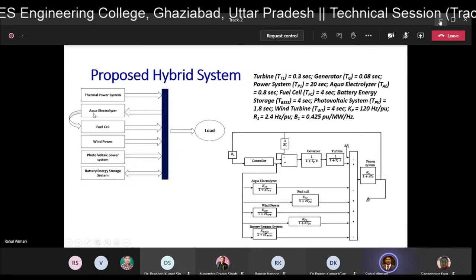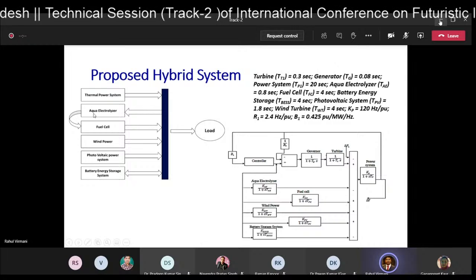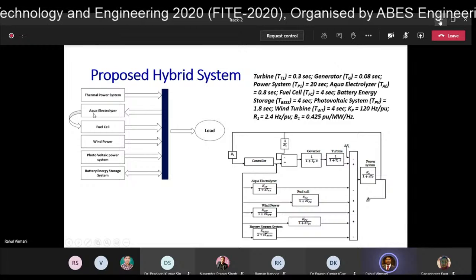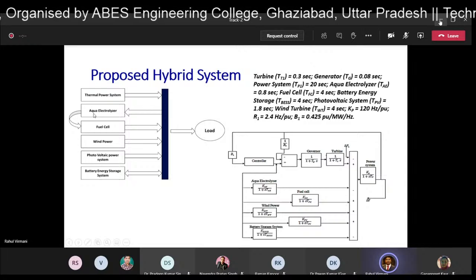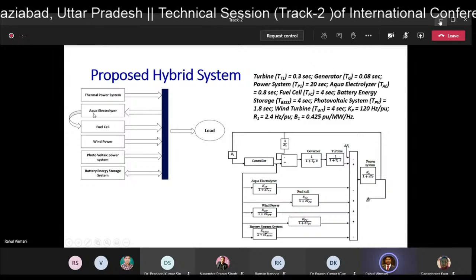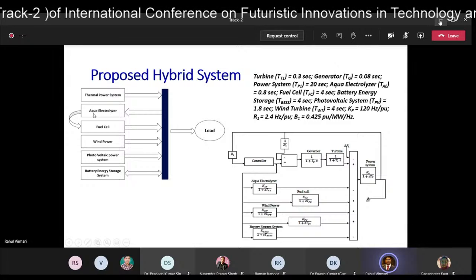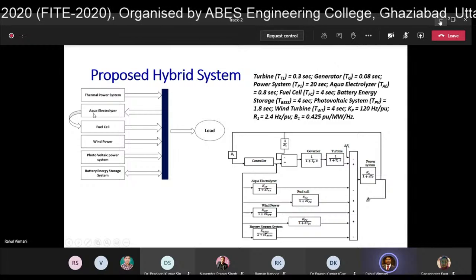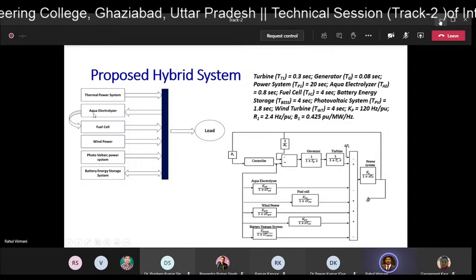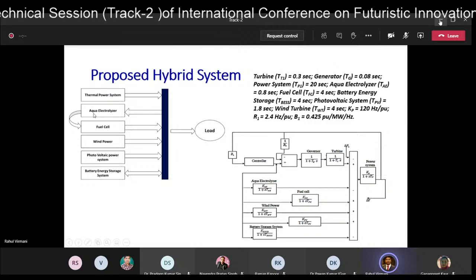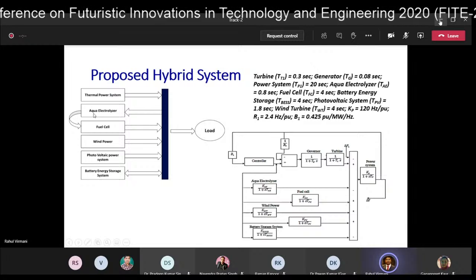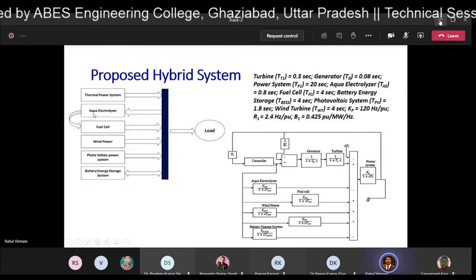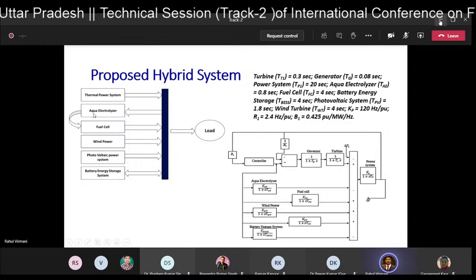Now in the latest techniques, I have used a fuzzy-tuned fractional order PID controller. Now you can see there have been a lot of changes in the system, although the efficacy of the fuzzy controller depends upon the rule set design. And I don't think they were properly optimized for the fractional order. So the response was not as satisfactory as what I required from it. But there was still a reduction in the settling time, the peak overshoot, the peak undershoot, and definitely the steady state error was also zero.